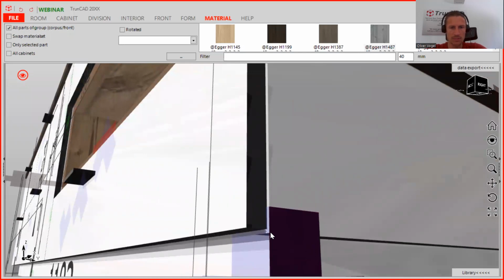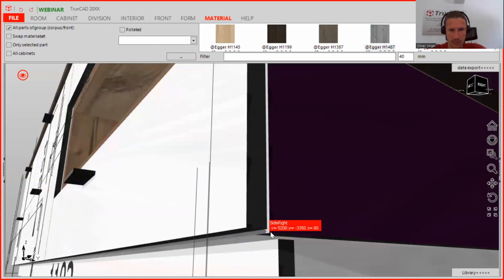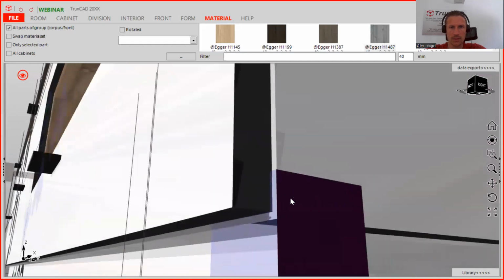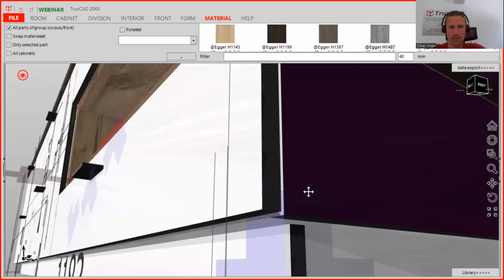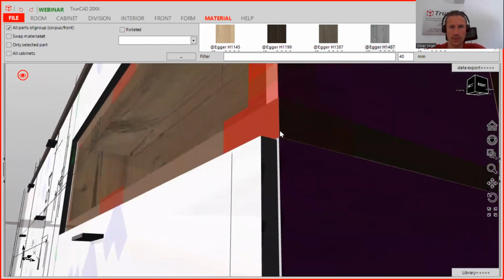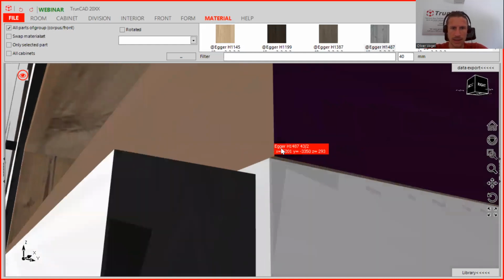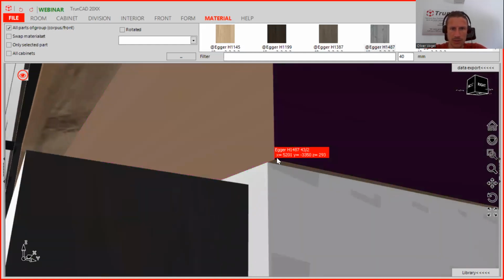So that's why you keep the control button, which you find on the left bottom corner of your keyboard. Yeah, you keep it pressed, and then you go here to this edge, you click it. So we pan up, and you keep clicked again the control button, and then we measure this point.